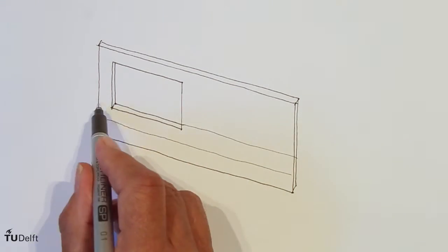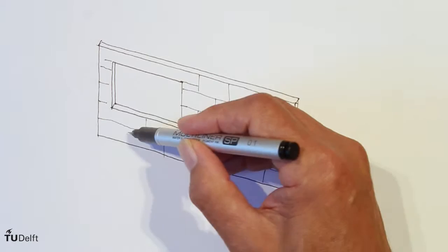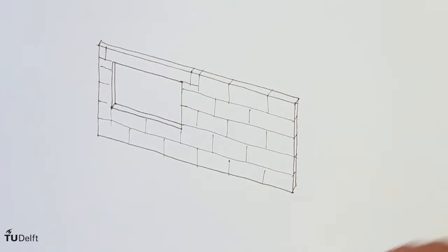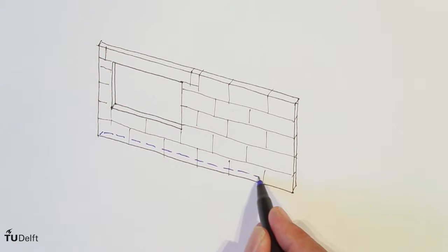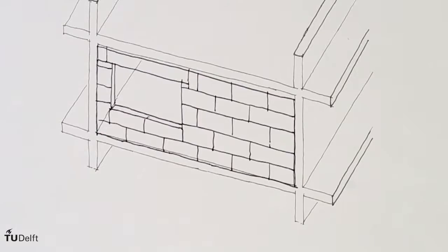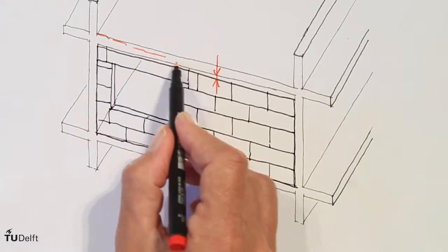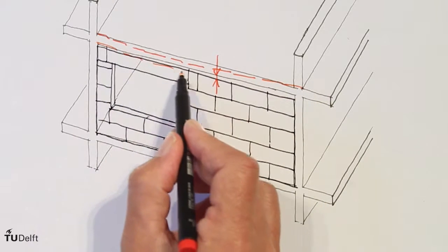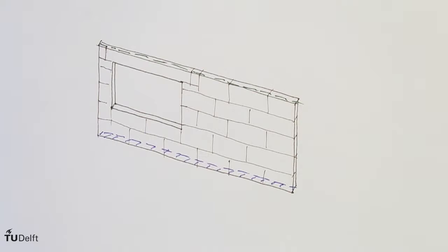The inner layer can consist of blocks in brick, sand limestone or concrete in a wide range of sizes. The blocks sit on the edge of the floor. As these materials are not suited for bending moments, wind loads are transferred to the floor by the weight of the wall. If the wall isn't carrying the floor, there should be a flexible joint between the wall and the floor above, so the floor can bend freely without having a structural impact on the wall.